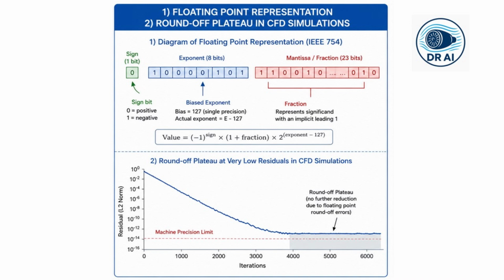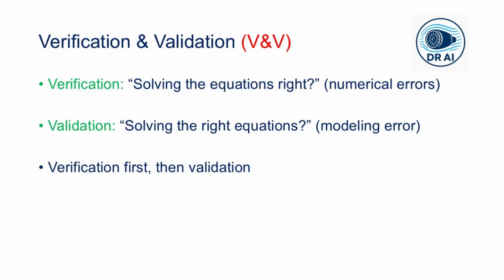In ill-conditioned systems, for example high aspect ratio cells, for the mitigation of this particular round off error, we use double precision. Single precision is very rarely enough for CFD. On the other hand, to avoid excessively tight iterative tolerances, use good preconditioners for the linear solvers.